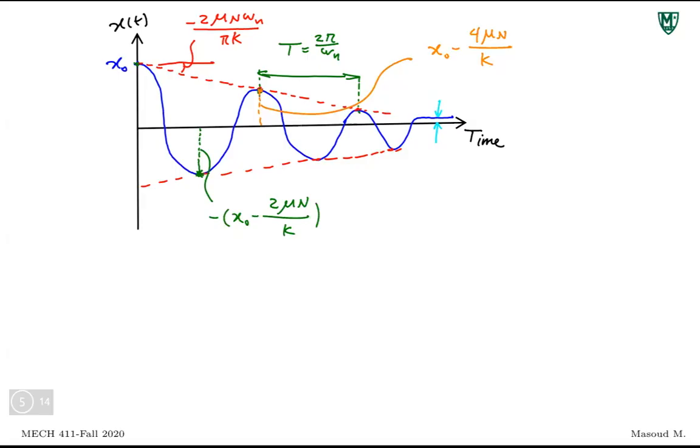If you think about that spring mass, we had N, we had mg, the spring was pulling it back, and the friction is stopping the motion, mu N. When it stops is when the force from the spring, kx, is not strong enough anymore to overcome the friction. So the moment it stops is the moment that kx is equal to mu N.